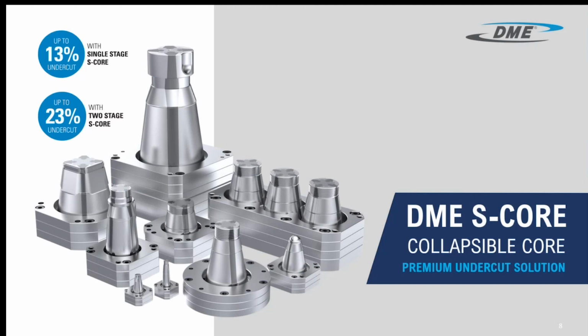So what we can see here is a range of our S-Cores that we have in different sizes, and with different possibilities of percentage undercut that we can use with these cores. So we start with a maximum of 13% for the single stage S-Cores, and it's up to 23% undercut with our two-stage ejector S-Cores. But it's up to the geometry how much percentage we can realize. Next slide, please.